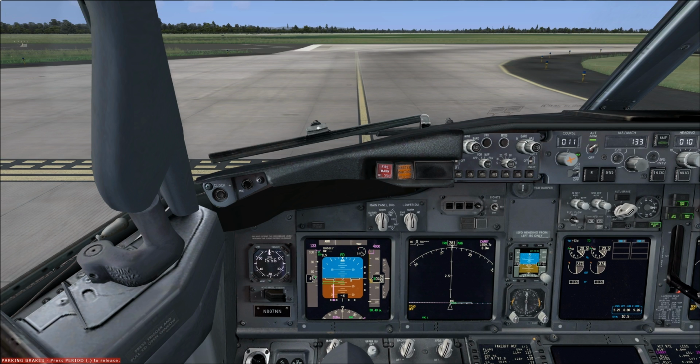And again, if you're not aware of what is happening, you'll get to VR faster, and when you pull back, the plane will fly because it's receiving more wind over the wings. You get to rotation speed, you pull back and you think for yourself, I got to VR pretty quick, okay, let's get flying. But wrong.